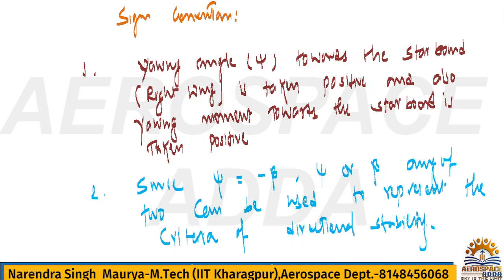So directional stability of an airplane is its natural or inbuilt ability to recover from a disturbance in the yawing plane about the normal axis. So if the aircraft gets a disturbance because of a gust or turbulence, it will have a yawing moment about the vertical axis because of the disturbance. Once the disturbance is gone, the airplane will try to come back to its original position.